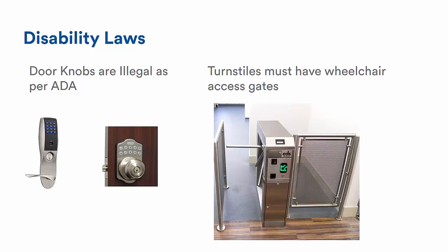So up until now, we talked about codes and standards that are published by fire protection associations in your local jurisdiction. We talked about how third-party conformity assessment bodies ensure that access control hardware will behave normally in reference to these codes. Then we have fail-safe versus fail-secure locking options based on the use of the door, like whether they are fire exit doors or if they're stairwell doors.